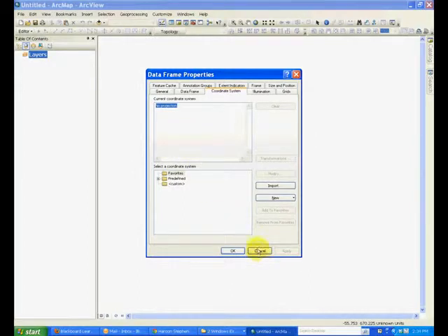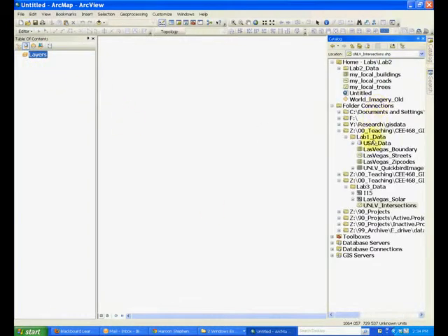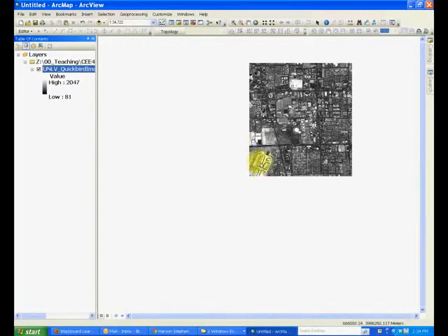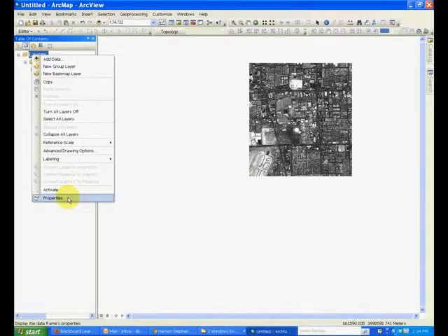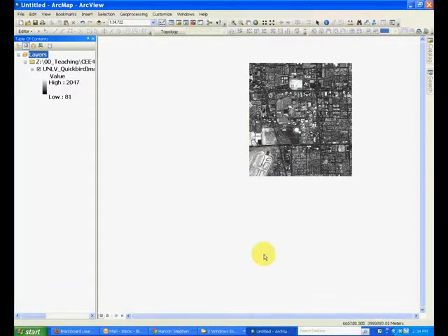Turns out it's the first layer, the first feature class or first raster image that you open in this layer, that will set the projection of this layer. For example, if you load the QuickBird image from your lab 1, and now look at the projection of this layer, you will see that it has been set to NAD 1983 UTM Zone 11N. And any subsequent layers that you add into this table of contents will be projected on the go to NAD